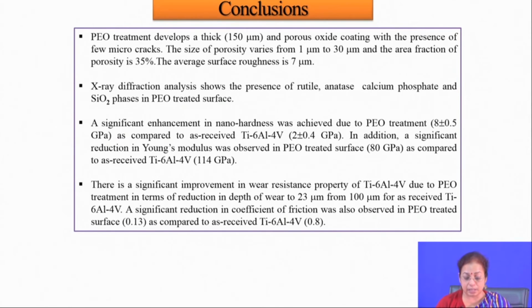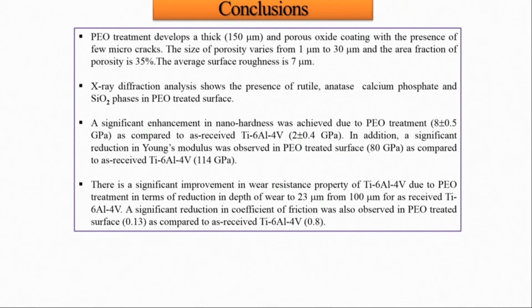So, the thin monolithic oxide layer acts as a kind of base for the subsequent oxidation. On the other hand, in case of anodizing or any other chemical conversion coating, the very thin oxide layer is the last point till when the process will continue. After that the process actually stops, but here the process starts beginning when the surface is covered with the oxide layer.